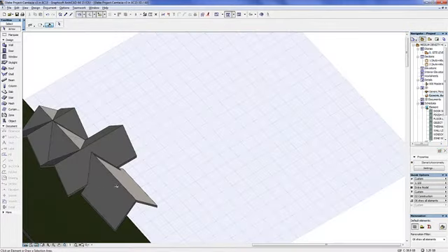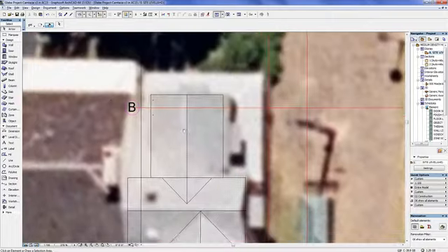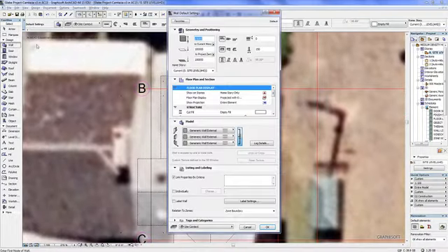Okay, so press F5 again so that we can see, and it's fixed this junction here, and we've just now got to put some walls in. And so we're going to put walls in a similar fashion to what we did here. If you can remember what we did, we went to the wall tool, made the walls 150, 50,